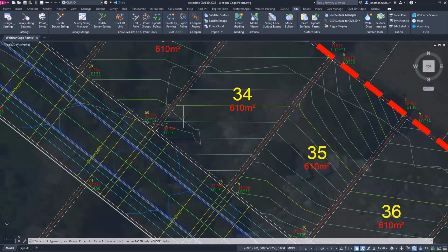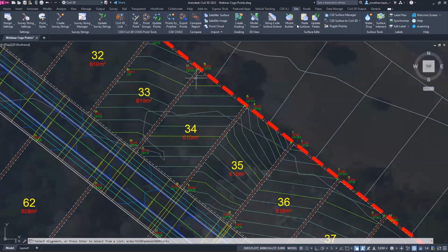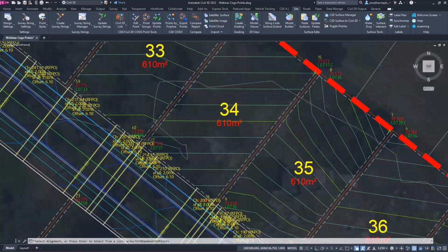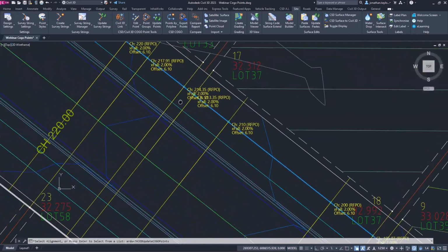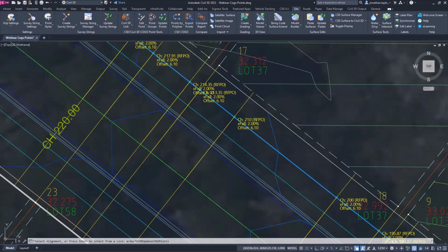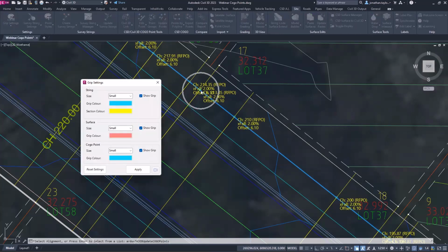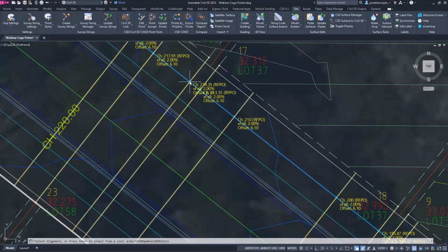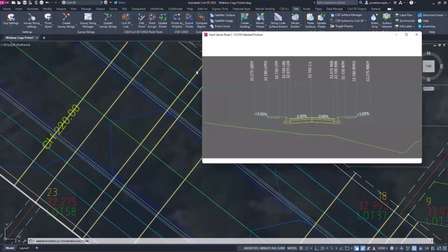Okay, so now we're going to have a look at the cross-section window. I just want to show you briefly. I did open the cross-section window a second ago, and I should have just kept it open if I'm honest with you. By the way, if you've never seen the grips before, I have mentioned them previously. They are basically set up under any one of the main tabs, apart from pipes, under the active drawing settings pull down grip settings. Okay, so my grips, these little grips here, are actually quite small. I like to have them quite small on the drawing. So this is where they come from. So I'm going to hover over this particular grip here and view cross section, much quicker than going up to the ribbon.